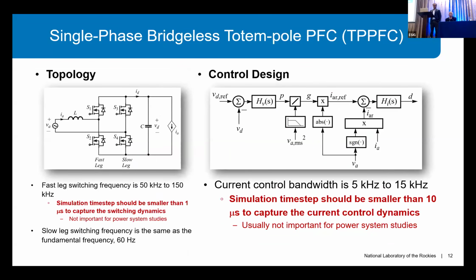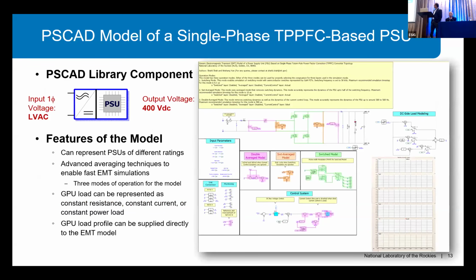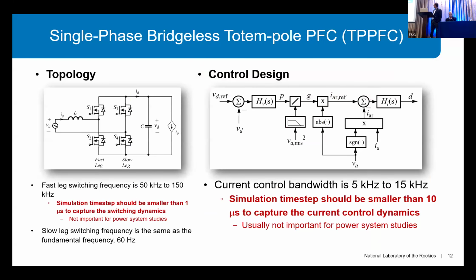So the PSU topology, or the power supply unit topology, that we are using for developing this EMT model depends on this single phase bridgeless totem pole PFC. It's the latest and greatest power electronics converter topology that is used in power supply units today for single phase PSUs. Now the tech industry is looking for 3-phase power supply units, and that will of course have a different topology, but we are still not there yet. And here is the control system.